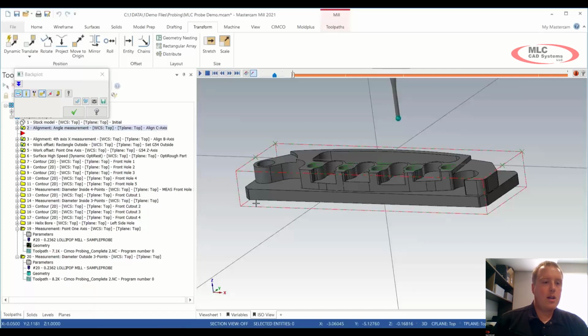And with that, we can put the probing routines really anywhere, on a current toolbar, a new toolbar, or a right mouse button click menu, and I'll show that here in just a second. Each of the probing operations is going to be considered an operation in my operations manager. That allows me, as with any normal toolpath, to go back in and change parameters. So again, with that being a standard operation, we can backplot those as needed.